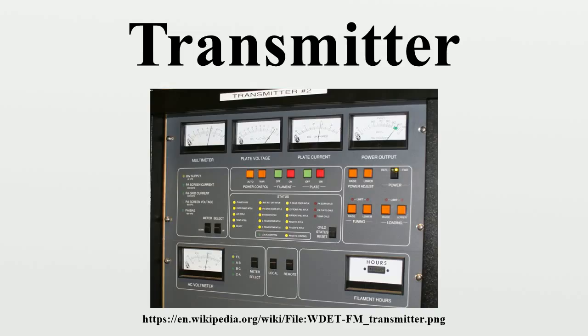In an AM transmitter, the amplitude of the carrier wave is varied in proportion to the modulation signal. In an FM transmitter, the frequency of the carrier is varied by the modulation signal. In an FSK transmitter, which transmits digital data, the frequency of the carrier is shifted between two frequencies which represent the two binary digits, 0 and 1. Many other types of modulation are also used. In large transmitters, the oscillator and modulator together are often referred to as the exciter.